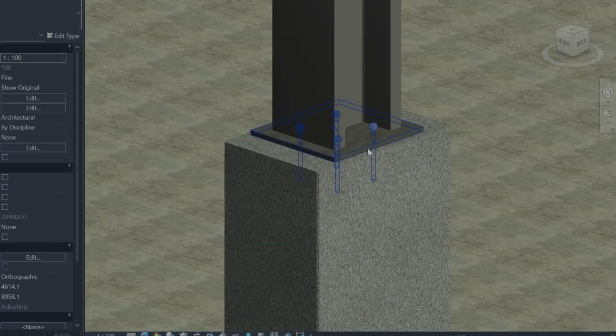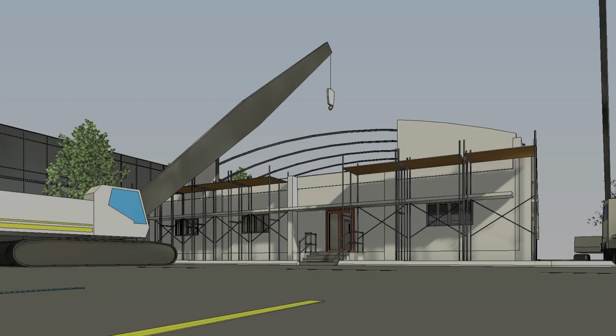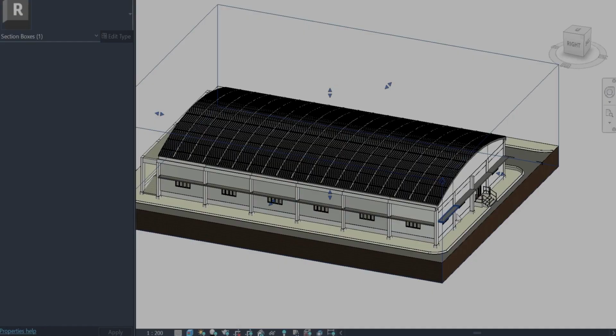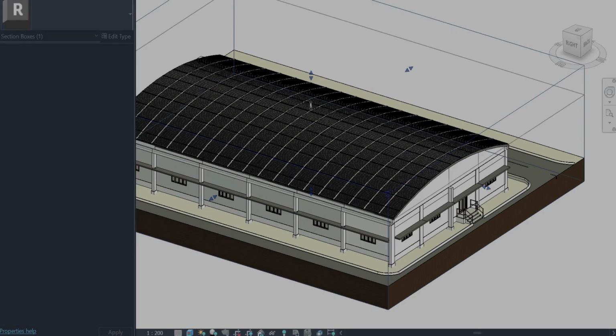They will definitely define the connection details of their elements for the design load calculations. With LOD 350, once you complete the decision of a connection among various joints, you will need guidance to install or construct the element in reality. This level is crucial during the design development for detailed coordination and analysis.